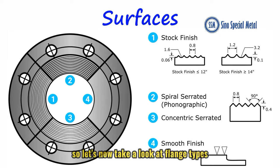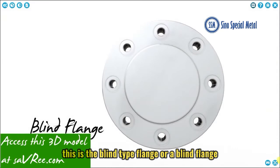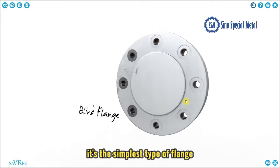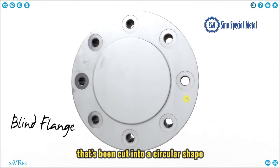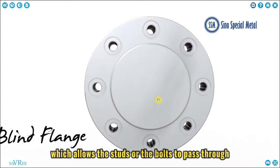So let's now take a look at flange types. This is the blind type flange, or a blind flange. It's the simplest type of flange that you're likely to see. It's more or less just a slab of metal that's been cut into a circular shape, and it's got some holes in it which allows the studs or the bolts to pass through.